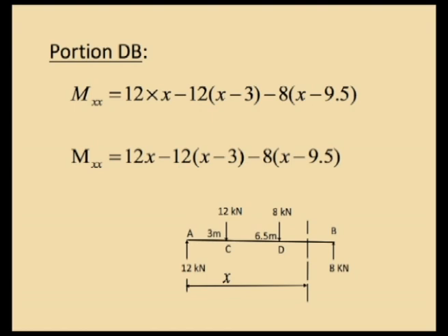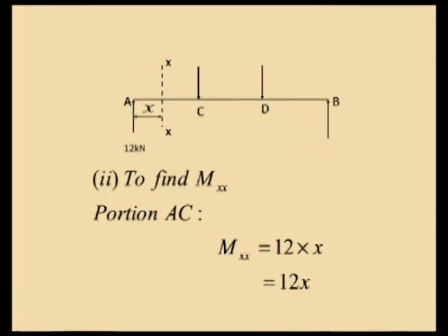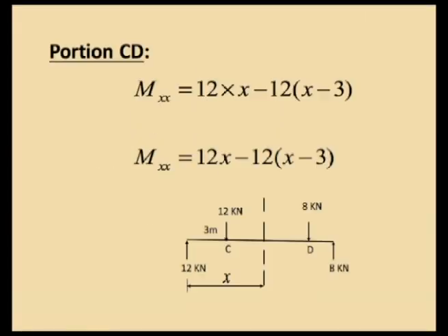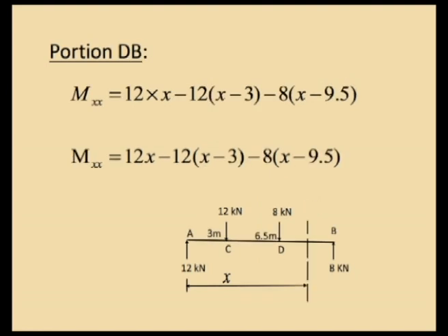So, the reaction produces clockwise moment while the applied loads produce anti-clockwise moment. So, plus and minus are assigned accordingly. If we notice the three equations, say the first equation is 12 x, and second equation is 12 x minus 12 into x minus 3, and the third equation is 12 x minus 12 into x minus 3 minus 8